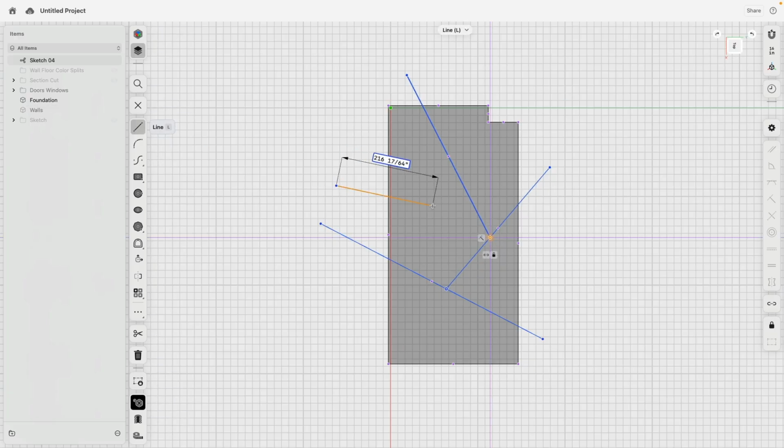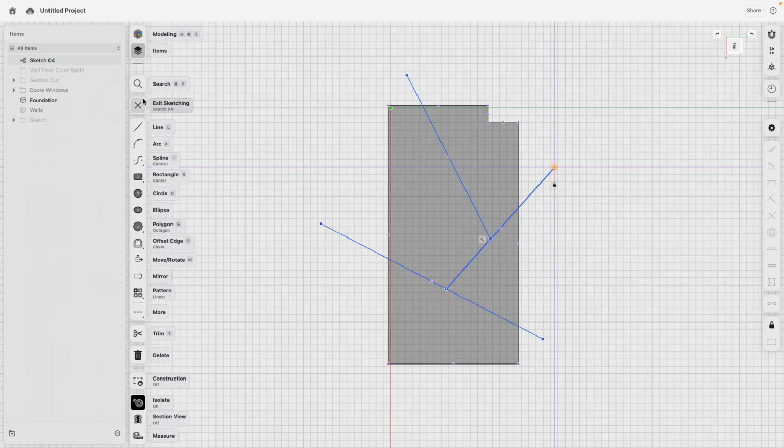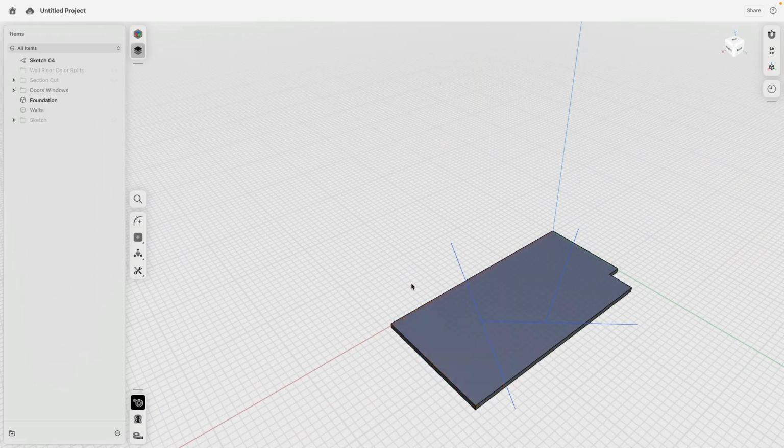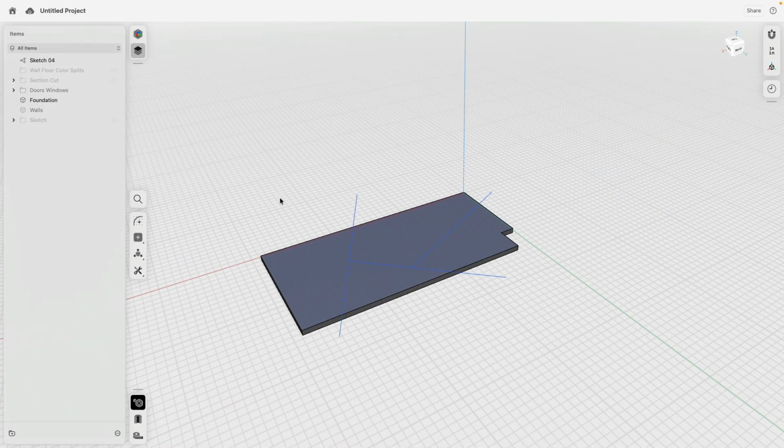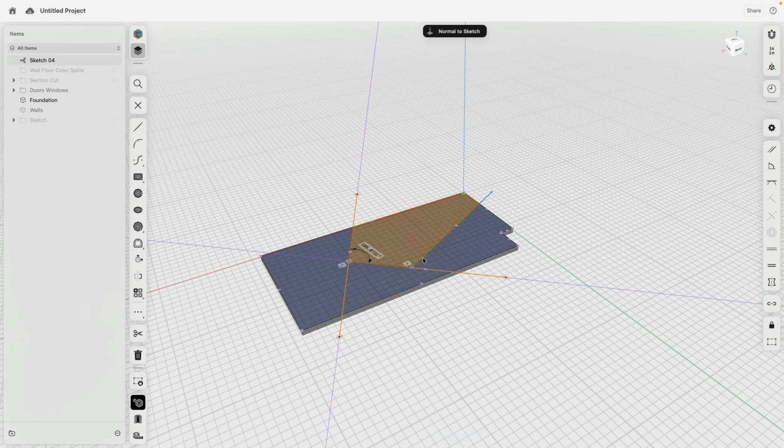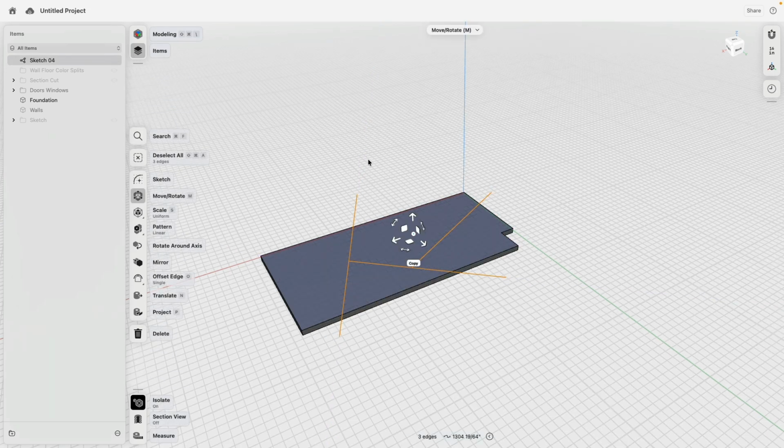You do not want to have lines end somewhere in openness or crossover, while this technically works. But when we do this, there's a fragment we later need to clean up. Extra work. So just draw it so they always end on each other. They can easily go over the body. That's fine.